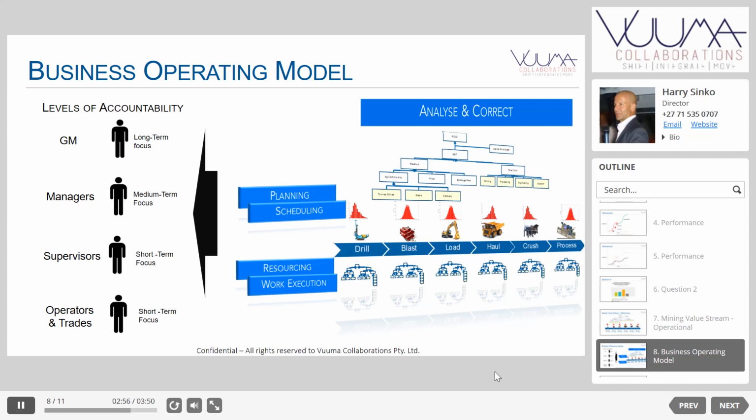Unplanned downtime. What are the reasons for unplanned downtime? There are 3 different ways that it can happen, maybe 4. One is that it's used outside of its design parameters. 2 is that the work that we did on it the last time, the time before, and the time before that was of low quality. We didn't do it well. 3, that we didn't use the right parts, the genuine bits. And the 4th one, anyone guess what the 4th one might be? The initial target was wrong.